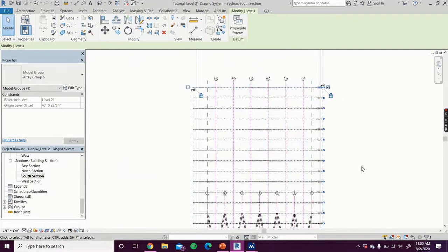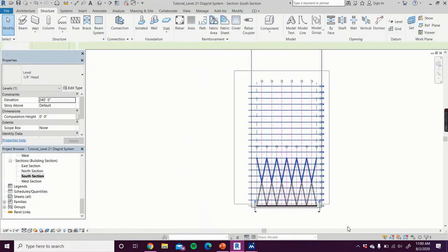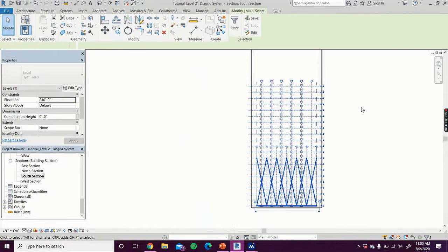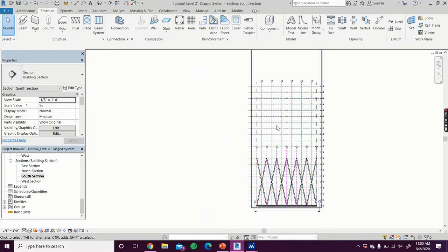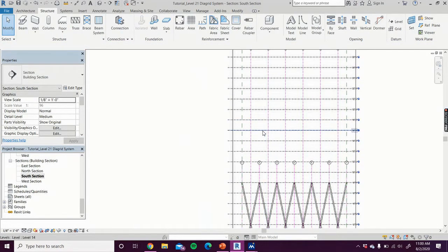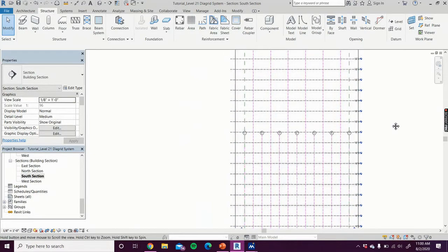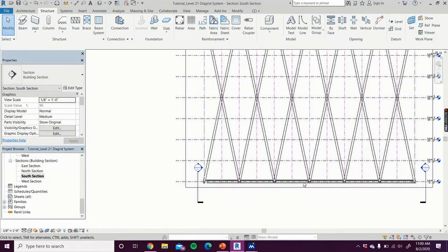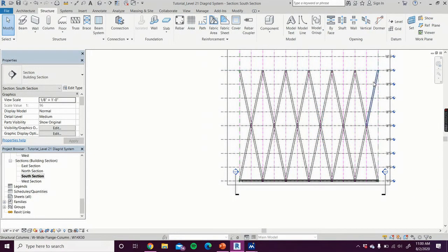Let's see. No dotted boxes. The dotted boxes are there for those little temporary grid lines we added, but that doesn't matter right now. So, okay, now we have our first columns on the first 9 floors, and we're going to repeat that same process for basically every section. I'm going to go ahead and do that now for all the sections and cut to when I'm done.